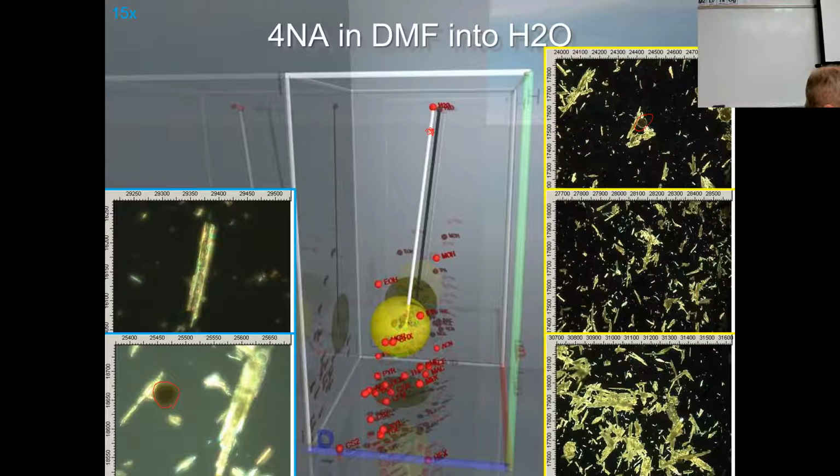Now, it's very difficult, as you can see down here, whenever doing these kinds of studies, to disperse your crystals. This data right here is unintelligible because the crystals are all overlapped. And so that's me showing you that I'm not a microscopist. Because one of the techniques in microscopy is dispersing your powder under the cover slip so that you can actually get separation between your crystals and you can look at them. So you may have this whole experiment, and this is speaking in general, but if you don't have good technique in terms of your microscopy, you can't analyze it. And so that's something that I would need to work on, my ability to disperse it.